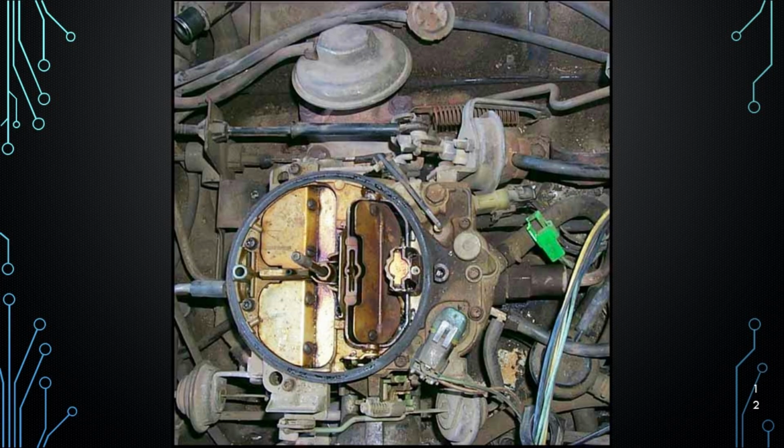Just above the EGR valve with a vacuum hose, that's likely a thermal vacuum switch. These switches are often threaded into coolant passages. They allow vacuum to flow, or not, based on engine temperature. When cold, it might block vacuum to the EGR. Once warmed up, it opens, allowing the EGR system to operate only at the proper temperature.